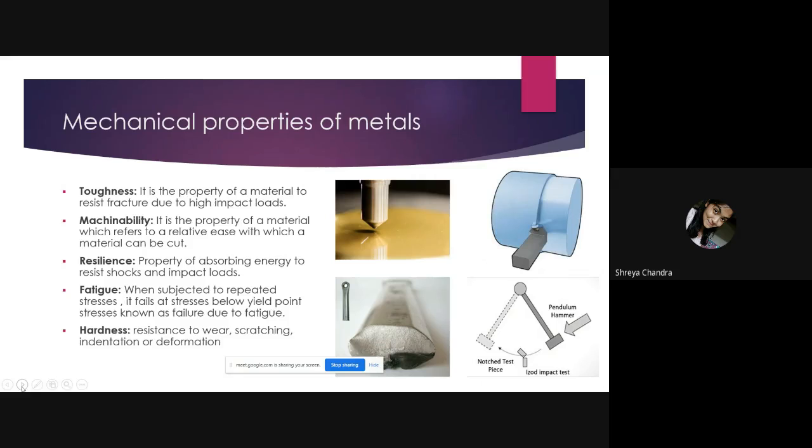Machinability. Machinability is the property of a material which states how easily a metal can be cut or machined. A good machinability indicates a good surface finish, that is, it should be equal in every place. The surface should not be rough and improper. A good machinability also indicates low force and power requirement too, with a long life too.